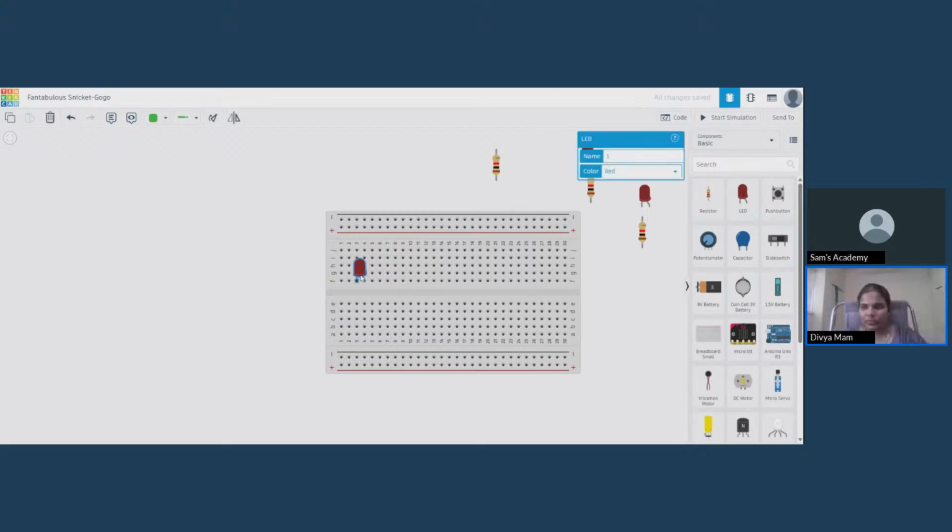So three LEDs, one here, three here. All right. So I'm going to make the GNDs common. So yes, GNDs. All the cathodes I'm going to connect to the common line, in parallel.